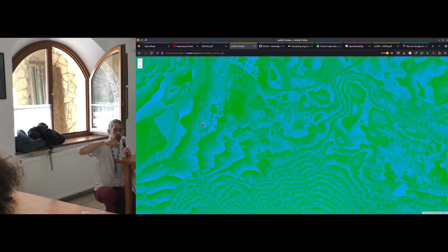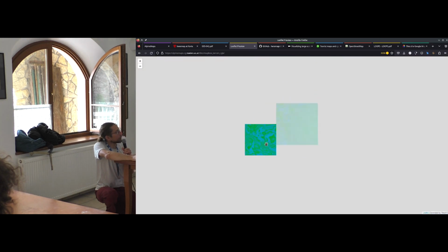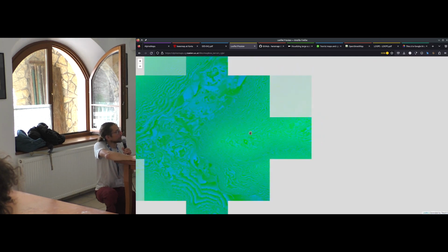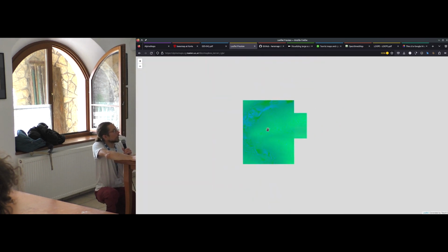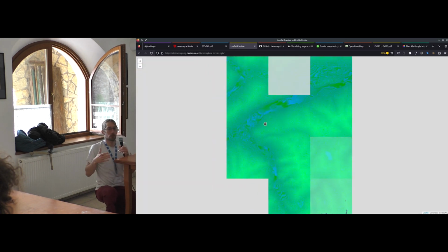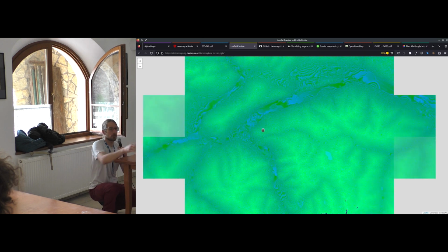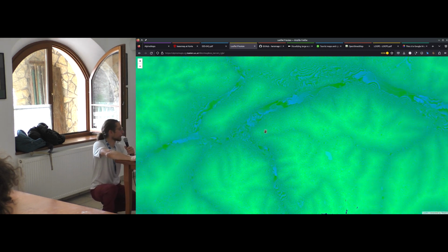So the green changes from 0 to 255 very quickly, and then on the border, when the green is full, the blue switches one bit further, one number up. So that's how we encode images, and in this case, I think it's a 24-bit encoding. So we have height with a 24-bit encoding.